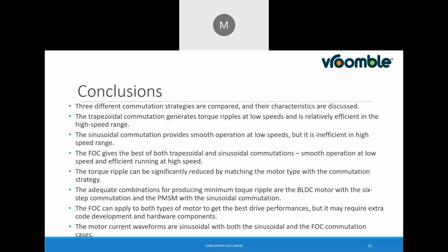Going with the magnet motor, the BLDC or PMSM motor, the advantage is the power to weight ratio. The compactness of the motor because of the magnet can be achieved very easily, and you get the same power density in a more compact size than the AC induction motor.